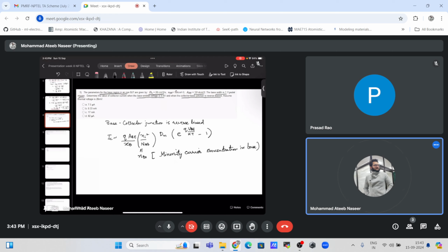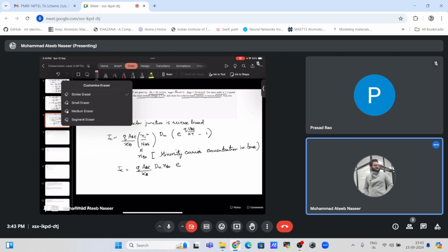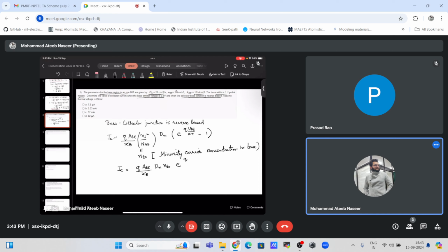So the IC will simply be Q times A divided by XB times Dn times NB naught times exponential of Q times VBE by KT minus 1.